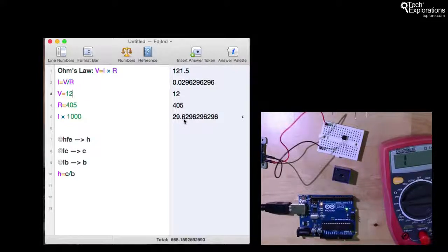All right, so now we know that we need to provide 30 milliamps of current in order to energize the coil. We need to get the power from the power supply when the Arduino says so. For that, we're going to use a transistor.